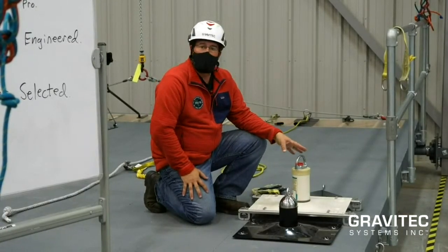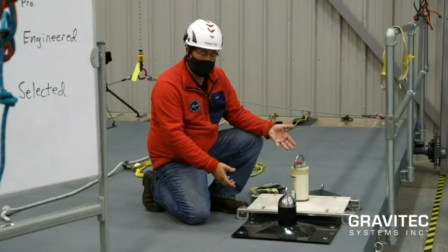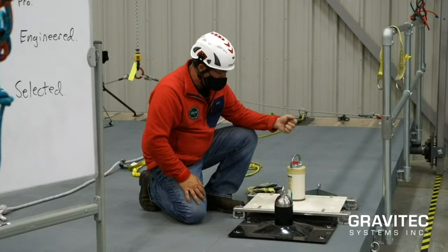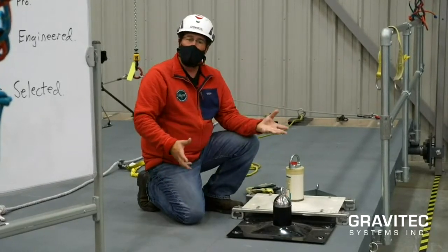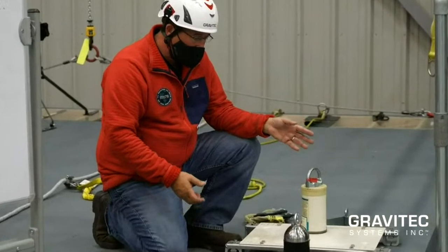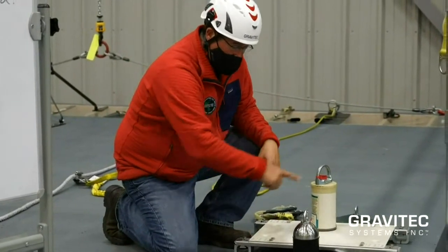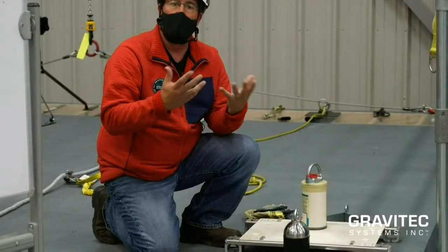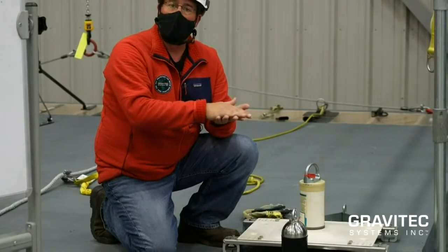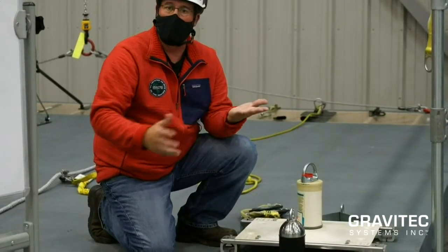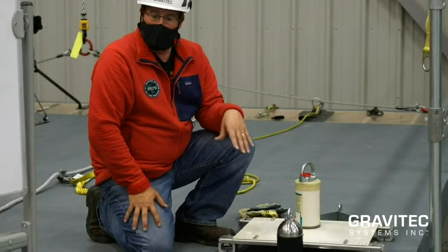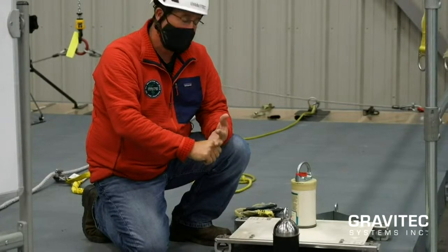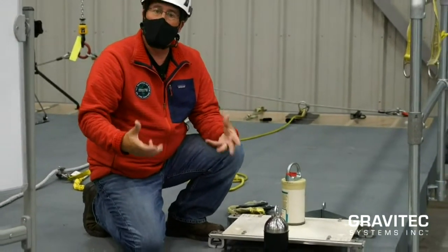Another couple common examples are these roof anchors or constant force posts. I've got two examples here. This one is MSA Latchways, and this is a Miller product. But all the major manufacturers have these, okay? What they do is there's a plate, and there's predetermined holes in each of these. And when you open up the user instructions, they'll tell you which holes and which connecting methods to use according to the substrates. So these anchors you can attach to wood, concrete. You can weld them to steel plates, or you can even attach them to metal roofs.